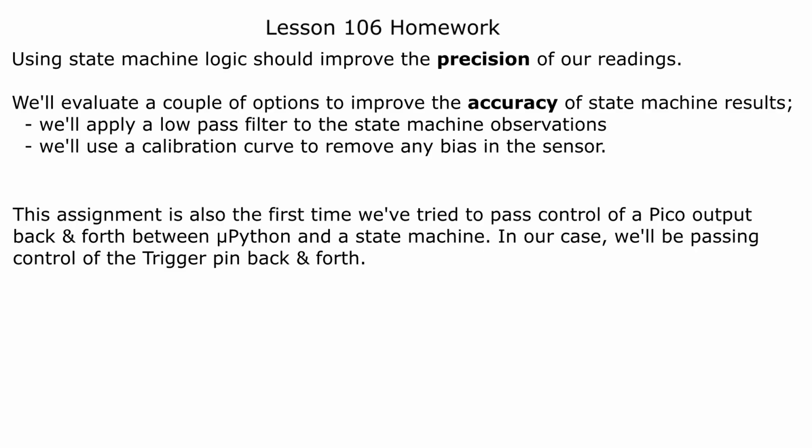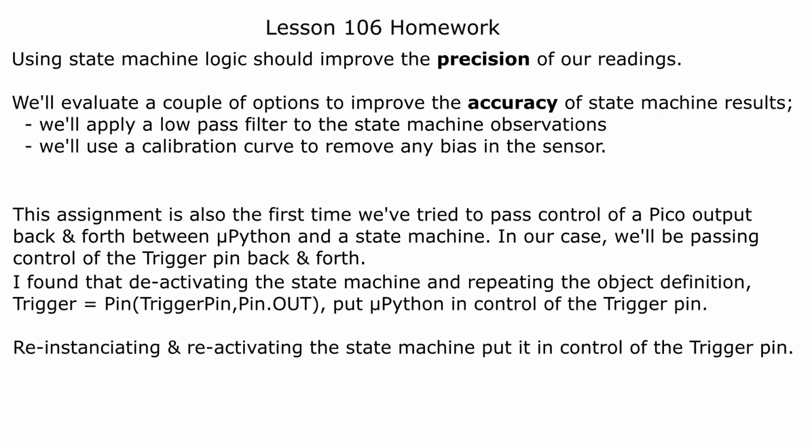and forth between µPython and a state machine. In our case, we'll be passing control of the trigger pin back and forth. I found that deactivating the state machine and repeating the object definition shown here put µPython in control of the trigger pin. Reinstantiating and reactivating the state machine put it in control of the trigger pin.